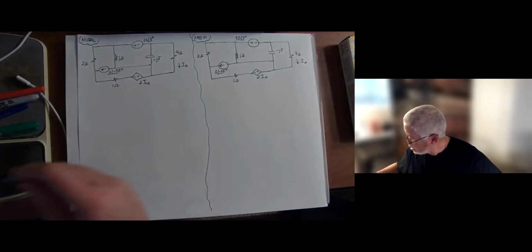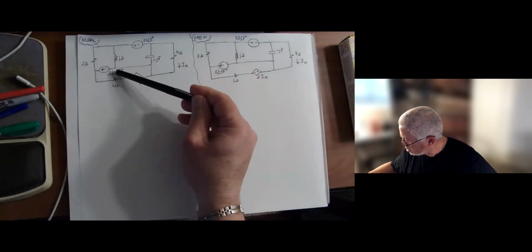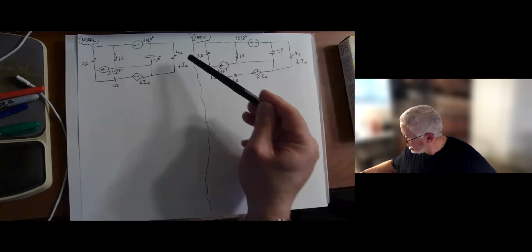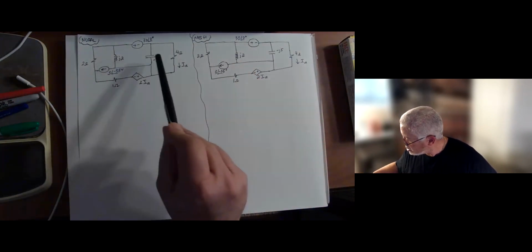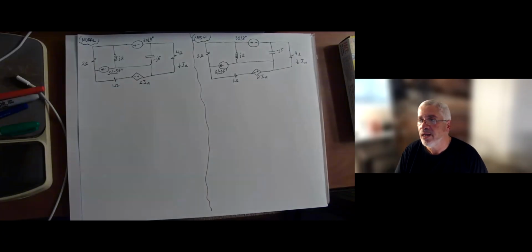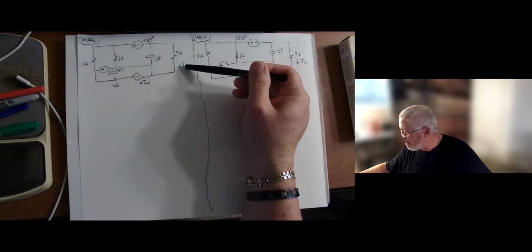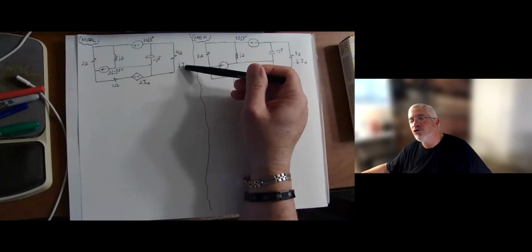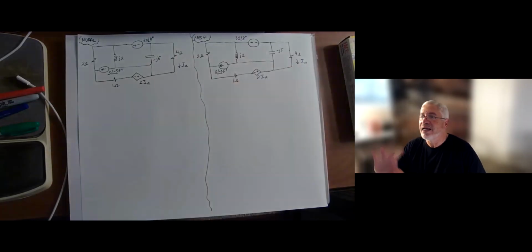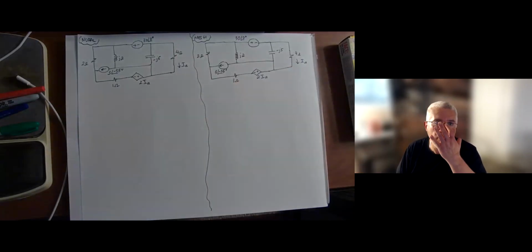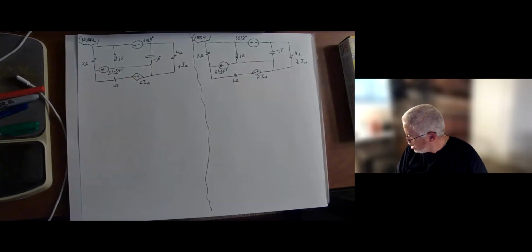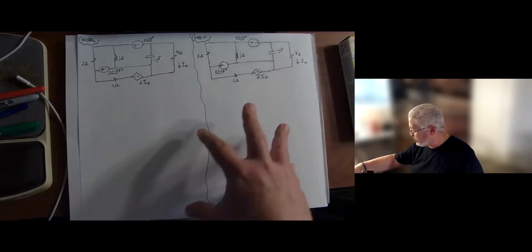Okay, so you can see what I was talking about here, converting the sources to their phasor representation, and also calculating the impedance for the inductor and the capacitor. The resistors remain the same. The other thing that we do, we tend to use capital letters to indicate the phasor form of the circuit, and we'll use lowercase letters to indicate the time domain, because remember, the phasor problem is slightly different from the original problem. Okay, so we are going to try to use this space very efficiently to come up with the nodal procedure, and then we'll do the same thing in mesh.